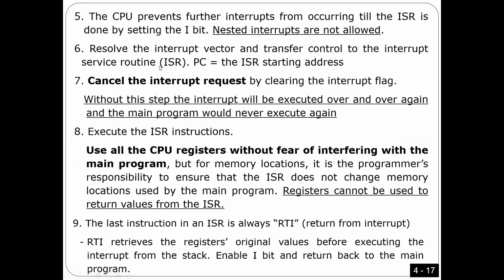Number 4, the CPU should prevent further interrupts from occurring until the interrupt is served. This is done by setting the I interrupt flag. Because I decided to serve one interrupt, I'm going to disable all other interrupts. Why, guys? Because nested interrupts are not allowed.